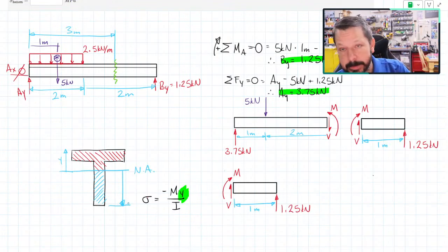And so you have different bending stresses. The magnitude for sigma is different because you have the same moment and the same moment of inertia. I is moment of inertia if you don't remember that. But the distance from the neutral axis, you have different distances. So it's sort of like a moment arm, but it's not really, but it's sort of like that.